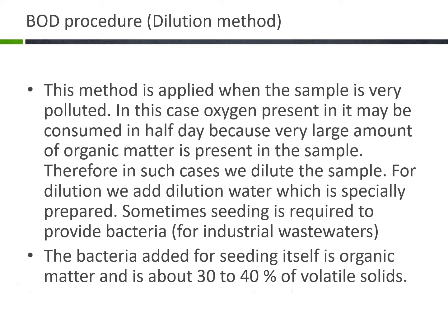Oxygen once saturated in the BOD bottles must sustain up to 5 days. But if the organic content is high, then all the oxygen within the bottles will finish within 1 or 2 days. So it will not give us a precise oxygen consumption rate because it is not completing in 5 days, but ended up in 1 day only. So we must sustain the oxygen saturation up to 5 days. How can we do it? By reducing the level of organic content.